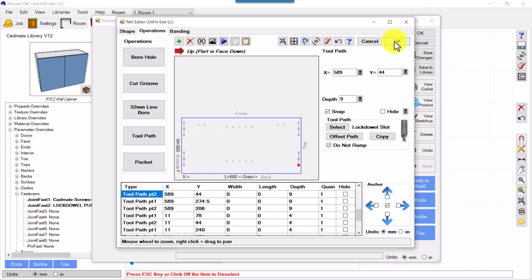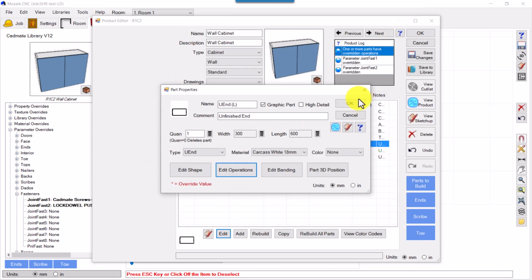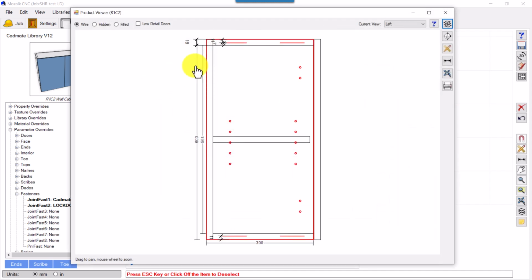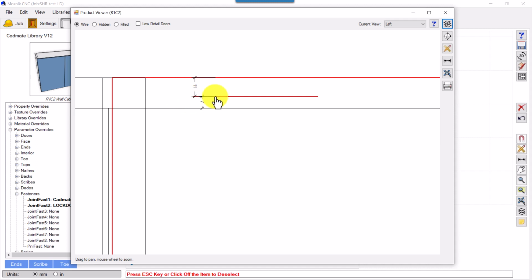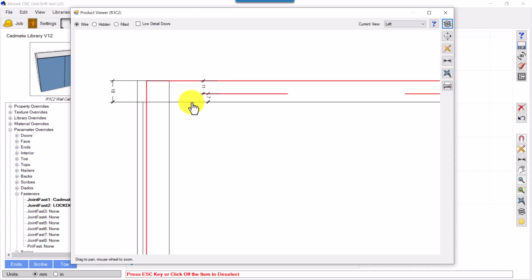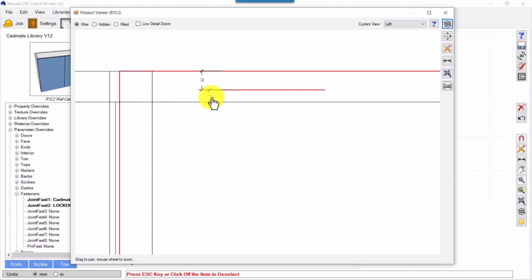So in this way we can compensate for the material removal which is required for the edge banding, and that is the edge banding thickness. So in this case we had edge banding thickness of 2. Suppose we have edge banding thickness of 1, then I'll show you. If you have edge banding of 1, then we just want offset of 1. So we want this to be moved upward by 1.